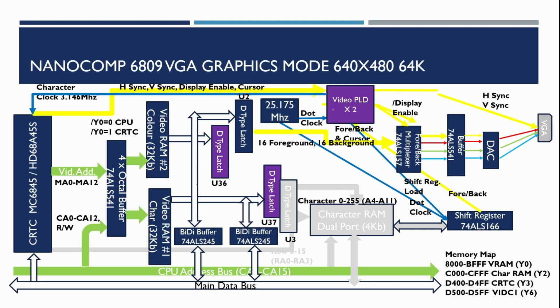And so the way we address this is by using 60 character rows, but then each character row has the 8 raster lines that we saw for the character generator RAM. So in fact, now we're making use of not only the memory address from the CRTC, but also the raster address lines are helping to generate the signals necessary to access the video RAM.